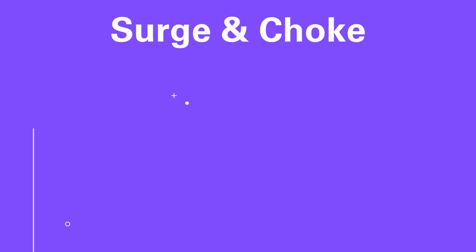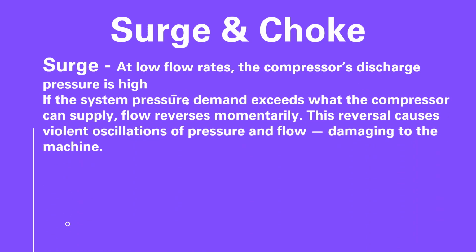Two things to be cautious of with centrifugal compressors, that is surge and choke. Now surge is something that happens at low flow rates when the compressor discharge pressure is high. So in other words, it's out of its pumping curve. Now if the system pressure demand exceeds what the compressor can supply, flow reverses momentarily. This reversal causes violent oscillations of pressure and flow and is damaging to the machine.